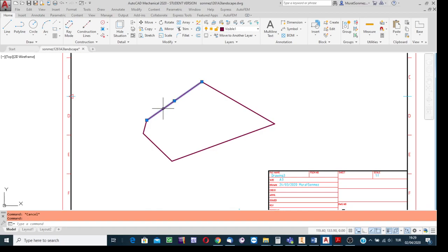Well, after indicating the line, I see the blue boxes at the characteristic points, terminal point, and this is the midpoint. Press escape button, indicate the other. You see we have lines in sequence, but well, these are not dependent on each other yet. Okay, these are independent lines because I created this figure using the single line facility.